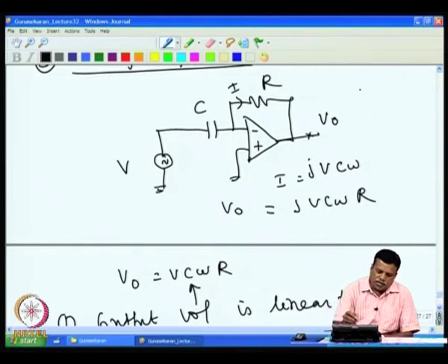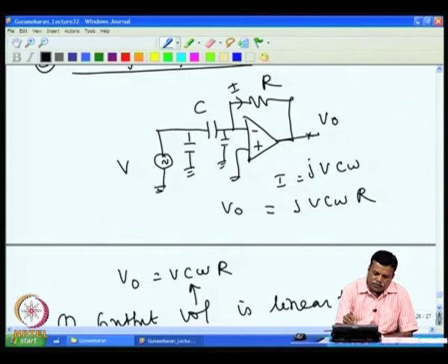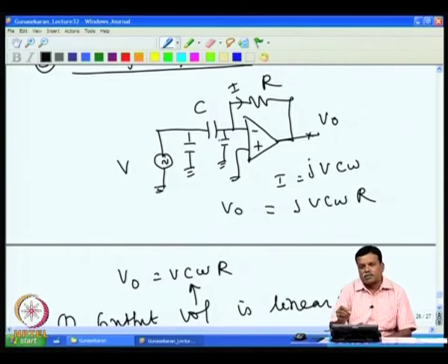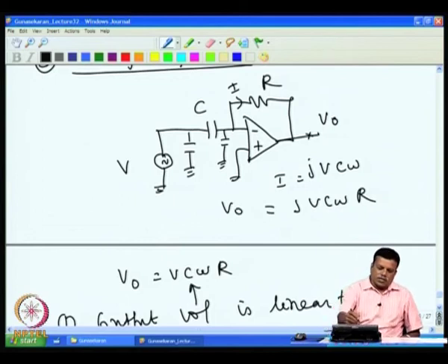Now, from our earlier discussion, stray capacitance is always associated with any capacitance measurement, because you will have a capacitance from this point to ground, mostly shield capacitance if you are using shielded wire. So, we will always have these two stray capacitances with any capacitor. That is why capacitor measurement is always considered a 3 terminal measurement, that is, you have a ground terminal 3, and measurement terminal 1 and measurement terminal 2.